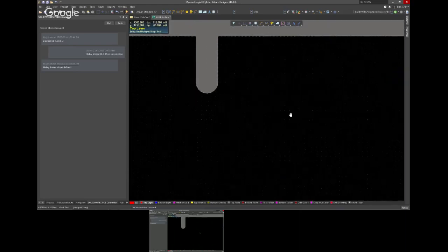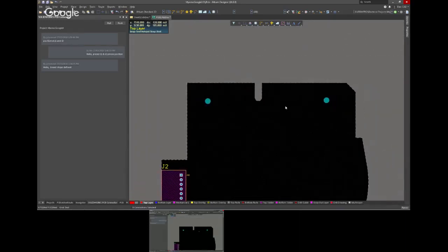Crazy question: what about flex circuits? Did you address that? No. Just rigid? Today is rigid, yes. We're looking at this whole flex thing, because some customers said they do it through sheet metal, and some use Altium to define it. Altium does not have stiffeners, it's just the layer configuration. So we said, we want to drive it right. You have the best two engines here, SolidWorks and Altium. How can we get this piece integrated and do it right? It's definitely something R&D is talking about today, and I give them my requirements, at least on what I would like to see. But today it just flattens.